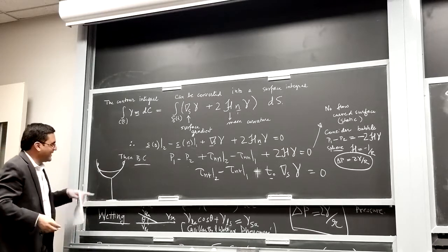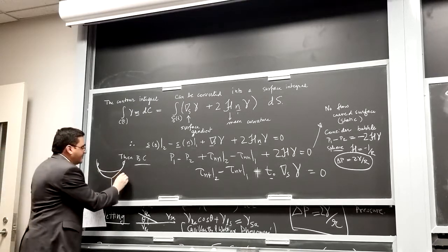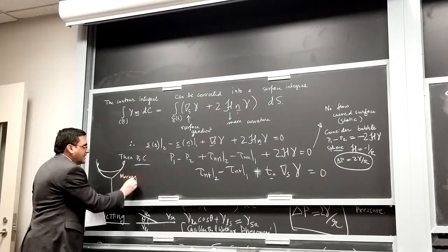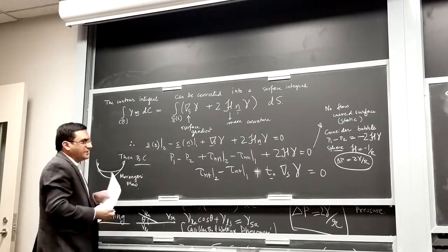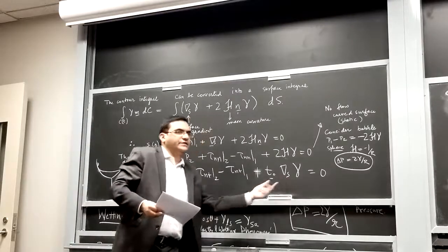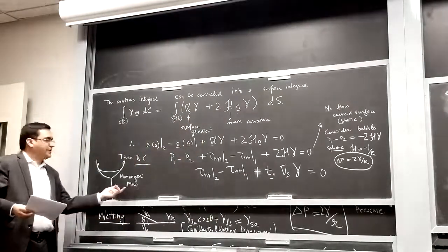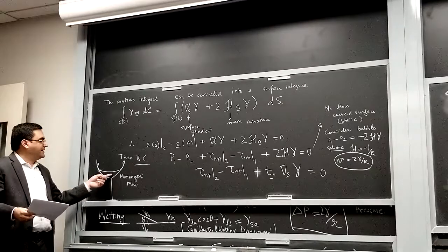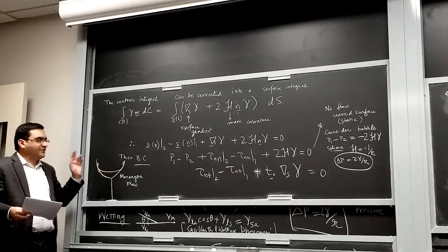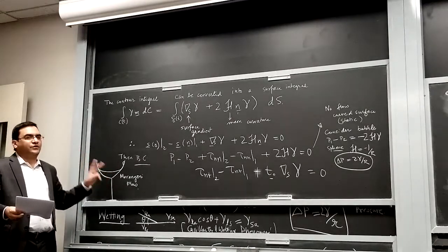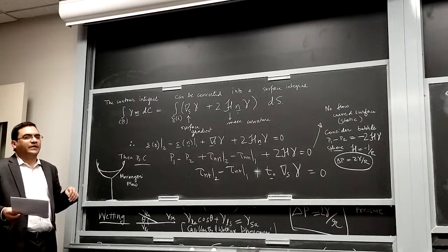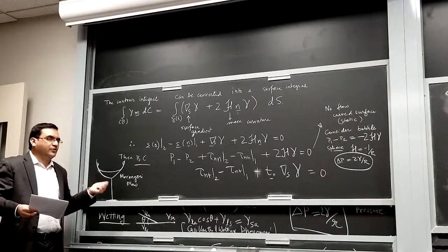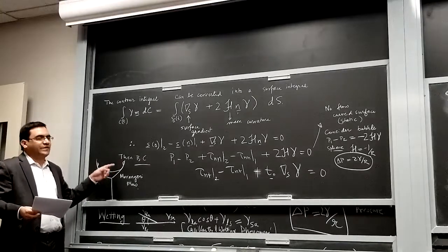So this is one example of so-called Marangoni flow. So whenever there's a gradient in surface tension that drives flow, it's called a Marangoni flow. And in this case, if it's a mixture of two fluids where one has very high surface tension compared to the other, and the low surface tension one is more volatile, then you can get something like this tears of wine formation.